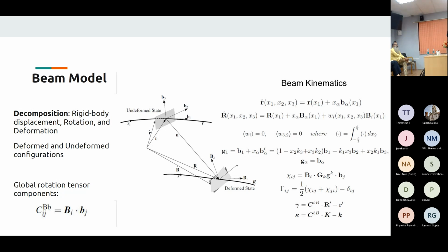So this is from the undeformed to the deformed state. It would be separating it into a rigid body displacement and the rotation of the deformed, and finally the deformations that would take place. So in the first two cases, it would be exact as it is. It's only in the deformations themselves that any of the approximations would come, depending on the type of strains that you're trying, if it's a linear or quadratic case. And then this is a very harmless looking term, which can become much more problematic, which I would be addressing in the future.